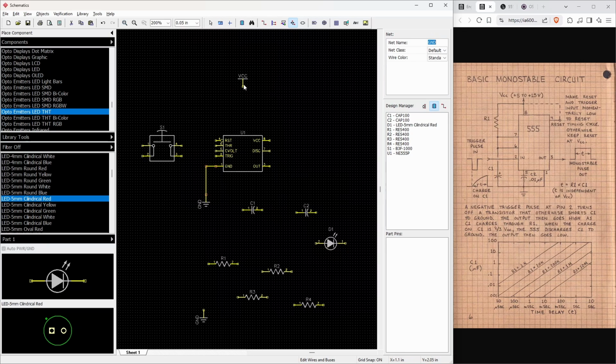Okay, so I'm going to go on to pin number 2, which looks like it's the input. Now this is interesting because the input here just shows something coming in, but for us, we're actually going to make it this switch. So let's connect it using a wire again. And then I'm going to connect the other end to ground. Yeah, so we want it to connect to ground so that anytime someone presses the button, it will go to ground, which is our pulse. If you look here, it's normally at VCC and then it drops to ground when someone pushes the button. So that's what we want.